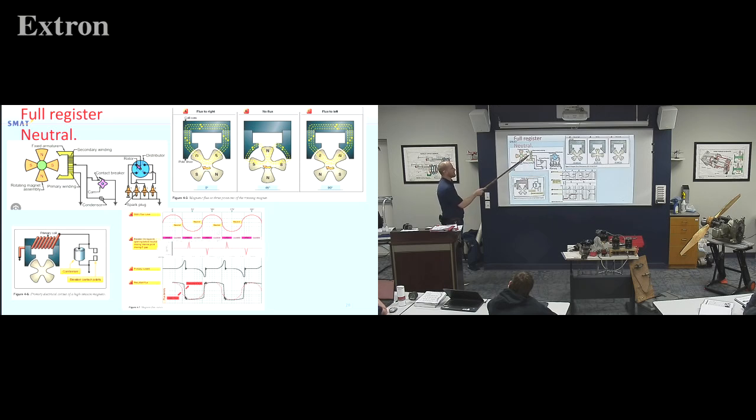We're going to cover how the coil's actually wired, but the secondary coil goes to our finger through the spark plug essentially to ground, and then back to ground. It would technically go through those same points, so every time we had a spark, we would spark across the points. That's not real good on the points, right?